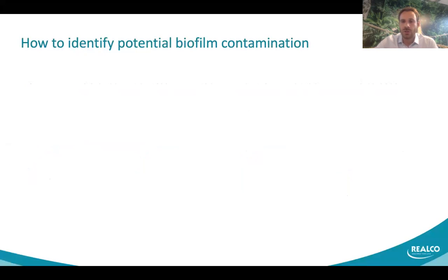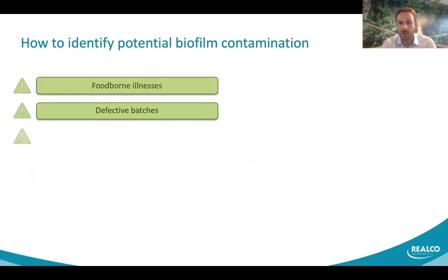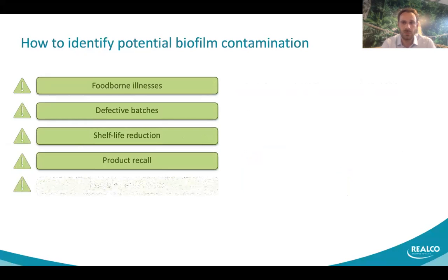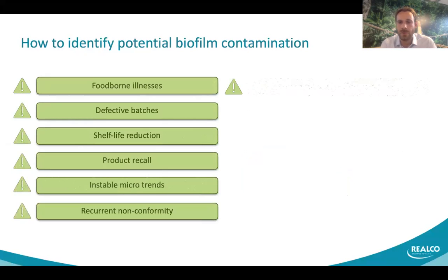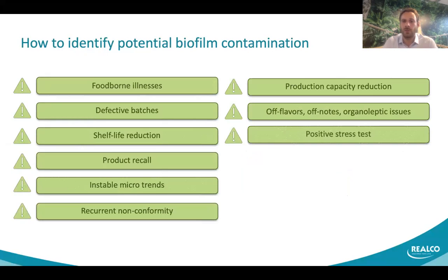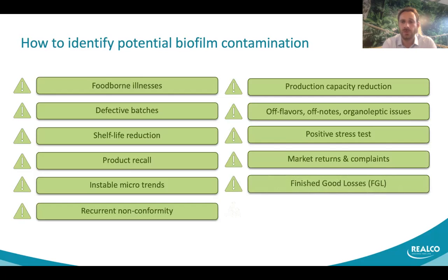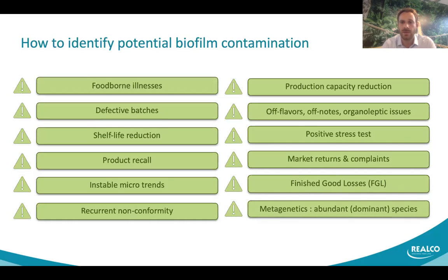You will ask me the question, okay, how do I know that I have a biofilm? In fact, there are some indicators that you may have a biofilm. For instance, when you are controlling your surfaces and you don't see the bacteria, and from time to time you see a high amount of bacteria, it can be linked to the presence of a biofilm. The biofilm is releasing at the time you make your control, and then you control again and there is no release from the biofilm, so you don't see anything. So that's the kind of tip you may use to detect the presence of the biofilm.